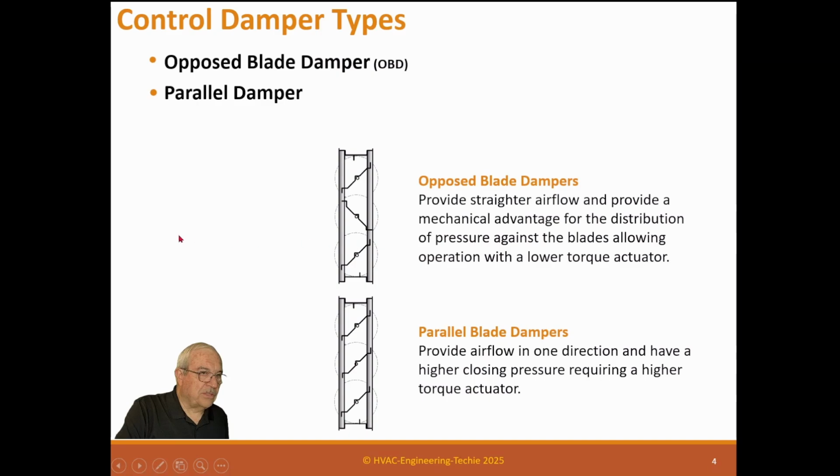So that you get these high stream jets going through here. And here at the edges, on this one, the damper actually forces the air down. So you're actually directing the air in a direction. This one is just straight, but it has jet velocity. This one is directing the air down as it closes. And that helps sometimes if you're trying to mix air in a certain direction. You can use a parallel blade a little more effectively.